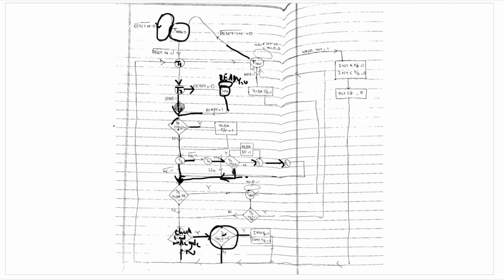In any case, it has to go to the T1 of the next machine cycle, and after execution of T1 only, depending on the previous instruction, it will check whether it has to enter the halt state or not. So this is your halt state. You can enter the halt state only after execution of the T1 of the next machine cycle. Depending upon what the previous instruction was, the microprocessor may enter the T halt state or may not enter the T halt state.